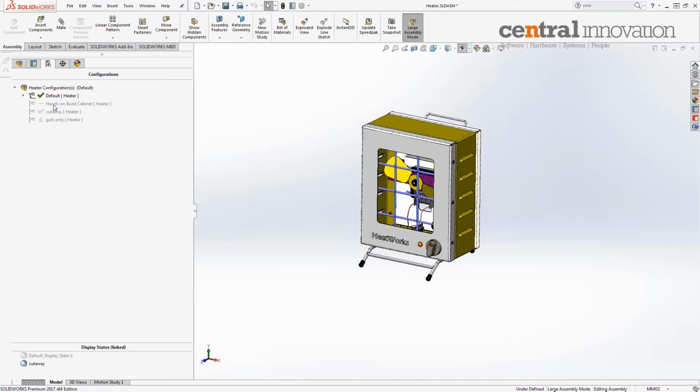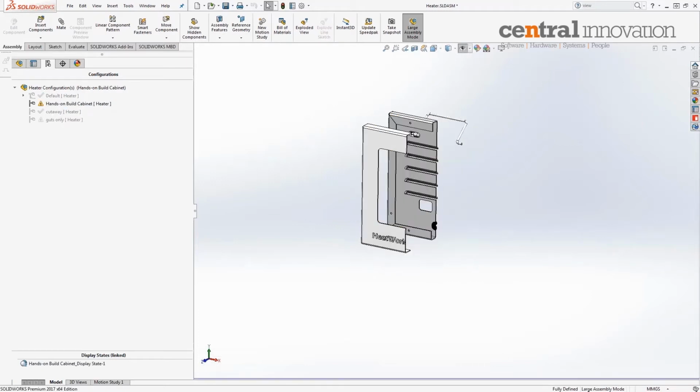The one that's got a dash next to it indicates that that configuration does not have its data currently available. It needs to be rebuilt effectively, and you can do that simply by clicking on that configuration, and it will rebuild that. Don't worry too much about that warning sign. There are some issues in that model, but it should actually show a green check there when it's rebuilt.